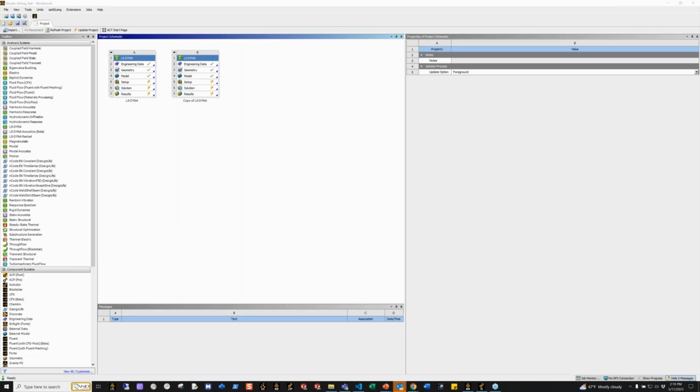One of the gentlemen earlier asked what the difference is between implicit and explicit. So imagine you have a problem that's very, very short in duration, like impact, but also has extremely large deformation. You really cannot do that kind of problem inside Ansys Mechanical, and that's where you need an explicit code. It doesn't have to be DYNA, but you're gonna need it. Now, some companies may not need to do these highly transient situations. Then you might make an argument that you do not need DYNA.